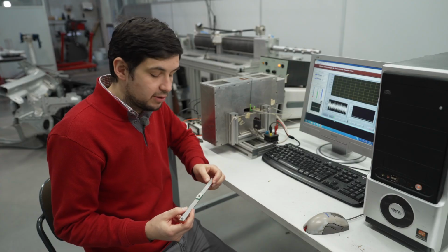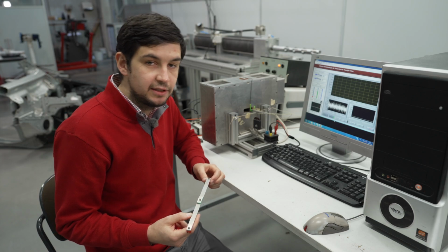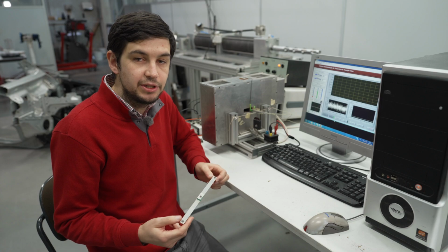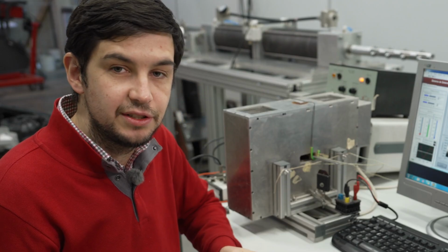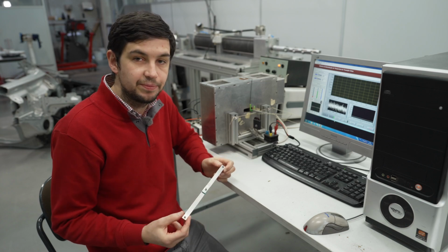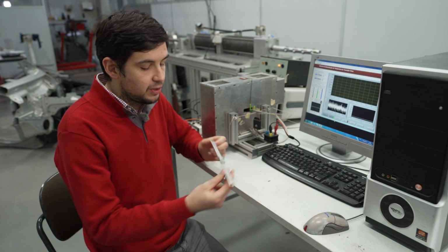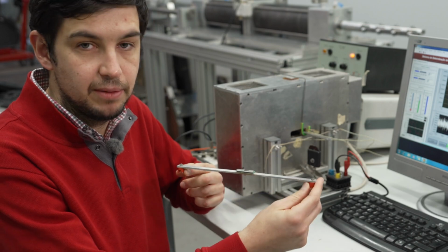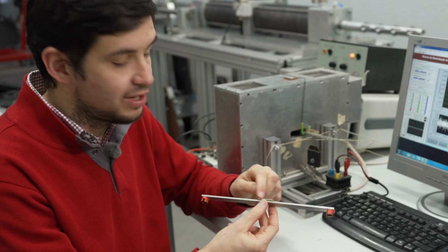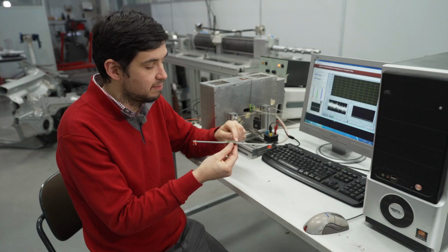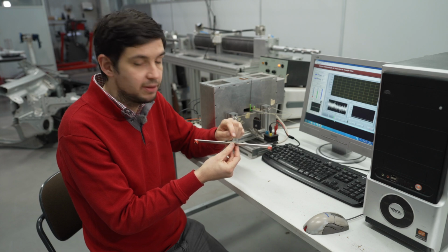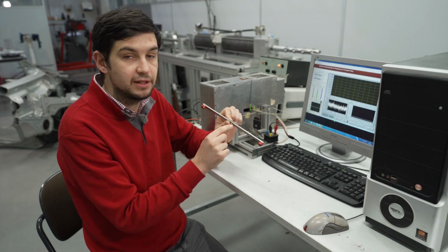I'm going to talk about this machine that we have that is called a glass transition temperature measurement device. This machine is used to determine the glass transition temperature of polymers, such as the adhesives that you see here. So how does this machine work? We have this specimen, which is a beam, and this beam has adhesive inside this constrained layer that you can see here. So there is a metal sheet. The adhesive is located here between the layer and the beam, and it's fixed in position by a screw.